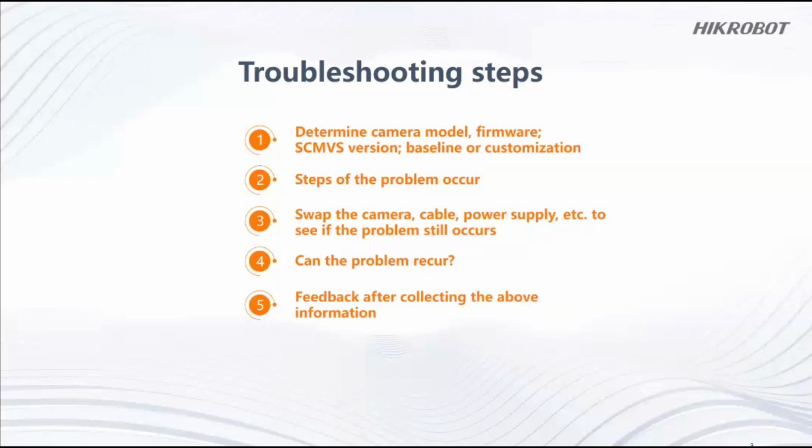And for the second step, we will locate when the problem happened and whether it can be repeated. And for the third, we will swap the camera, cable, or power supplies to see whether the problem will still occur or disappear.